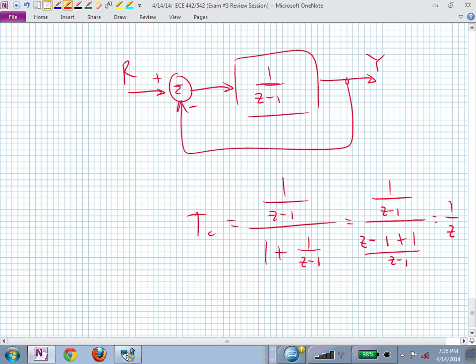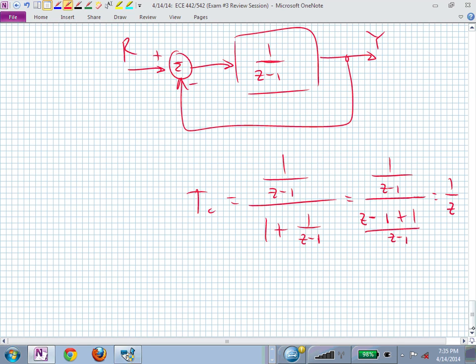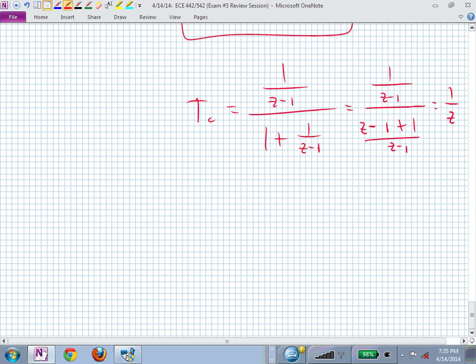That's the design by Ragazzini. And you could make this much more interesting. I could have you doing something other than a deadbeat response. I could say, I want your poles to produce a certain settling time, a certain peak time. That's going to give you an R and a theta sub D. You can now find where those poles are. You might have to incorporate some of those restrictions. Are there questions on Ragazzini? Yes.